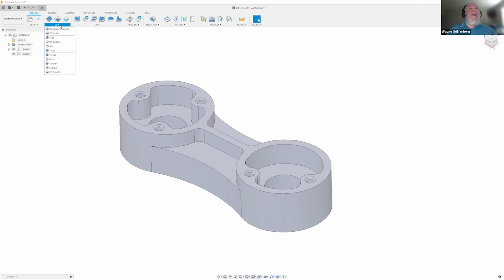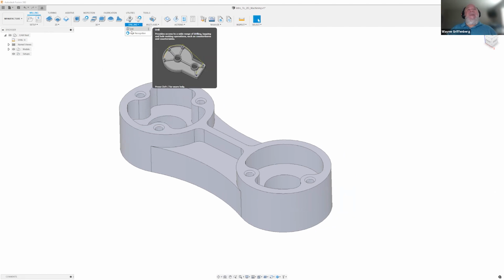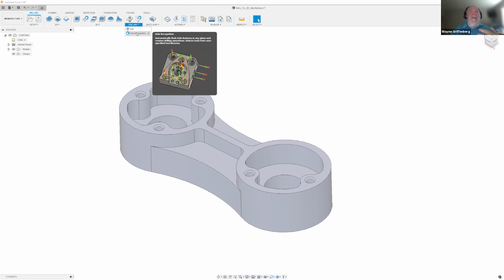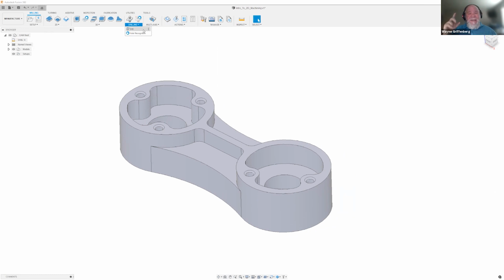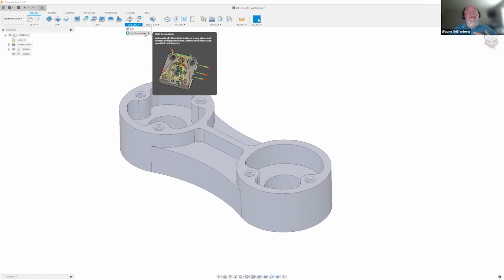Again, I just want to let you know we do have the 2D toolpaths, some 3D surfacing toolpaths, and drilling. Wherever you see these little plugs, this is an extension. This is where you can extend your capability. We have a robust drill workflow where you can set up all your drills for your holes, but you can add and turn on the capability coming from FeatureCAM, running directly inside of Fusion 360, which will add an automated tool that'll select all the drills, like the pre-drills, the spot drills, the taps. If you have all those holes in your part, it's going to grab all those tools from your tool library. So you have ways you can automate that process as well.